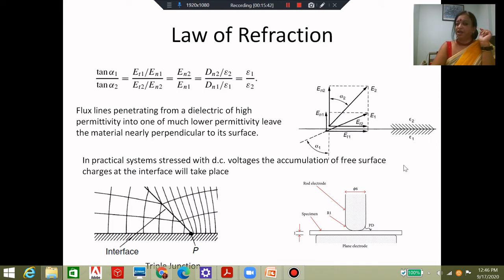I say that the material epsilon 1 has a conductivity sigma 1, and I have also assumed that sigma 1 is less than sigma 2, which means the number of charges which will flow from this boundary towards, let's say, the other electrode will depend upon sigma 1. And if sigma 1 is less than sigma 2, the number of charges flowing across this material per second will be more than the number of charges flowing out of the interface through this material per second. So if 10 charges are coming in per second, let's say only 6 charges will be able to flow out.